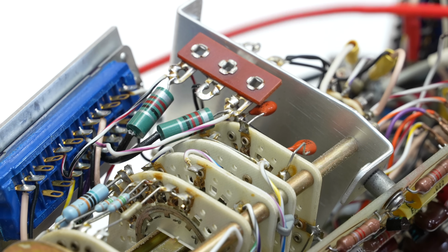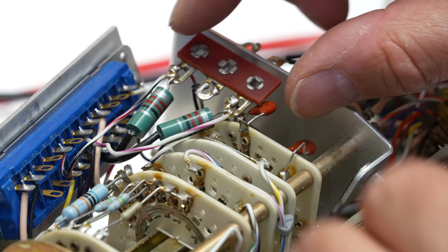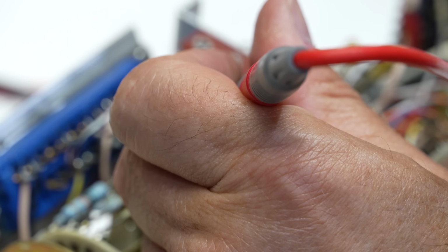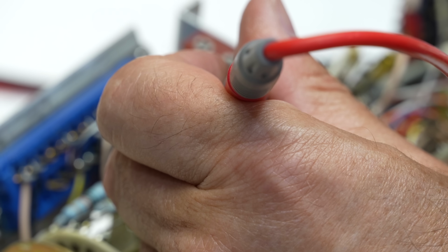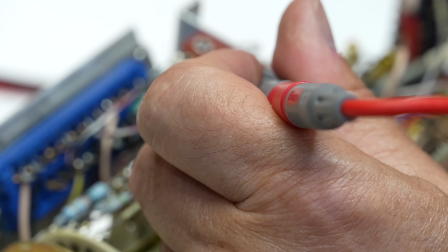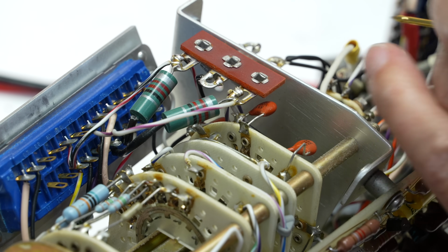Okay, it's connected to minus 12.6 volts, but also connected to my wafers with all the caps. And my theory, untested, but we'll know in a second, is that this has been pushed in, and it should be like this. And now let's try my cap again, and minus 12.6. And the short has disappeared. Minus 12.6 is here. It's not there anymore. It's not on my wire anymore.